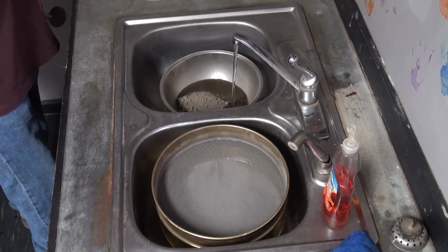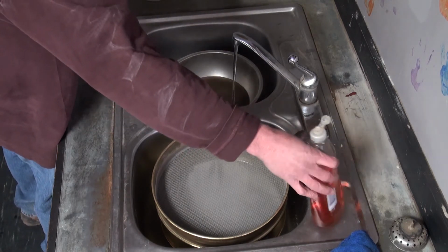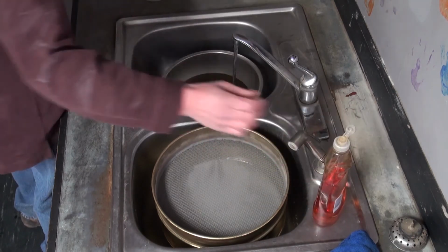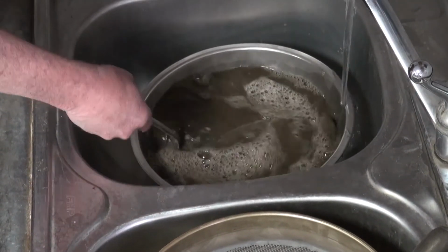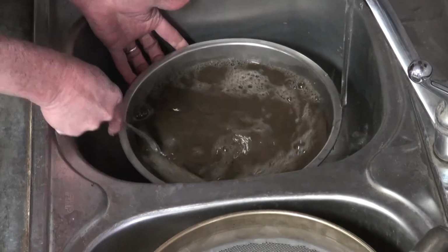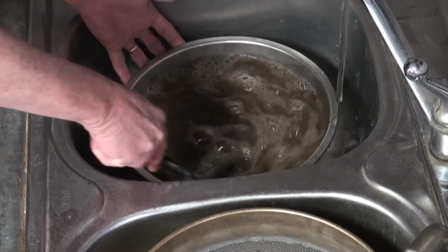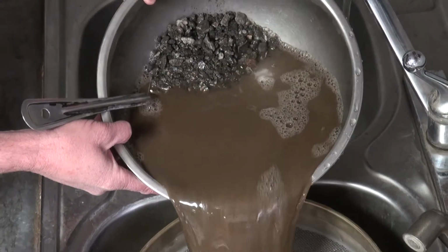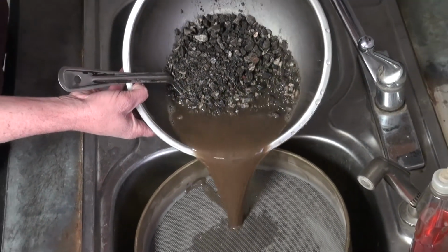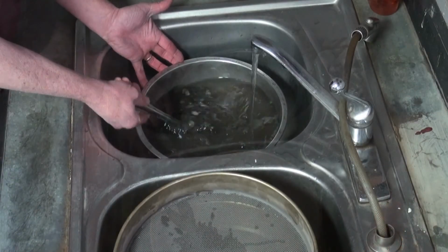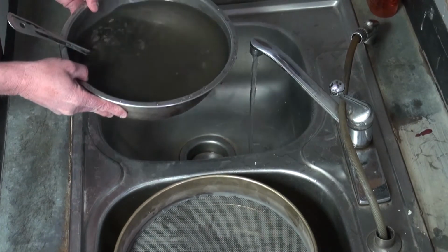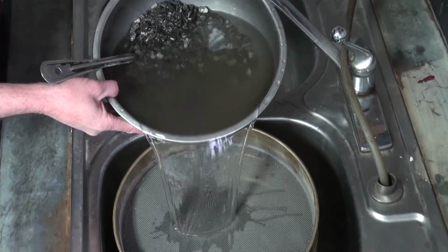For this video, you can see the technician is actually going to hand wash his sample. Either process is permitted, whether it be by hand or by mechanical washing. There he is adding a drop of a wetting agent. Basically any kind of soap you've got is your wetting agent. Okay, and notice how dirty the water is here. And he's going to decant, or pour, the water through the same nest of sieves, which is a number 16 sieve, and below that is a number 200 sieve. So he'll continue to do this several times, 6, 8, 10 times, until the water gets clear.